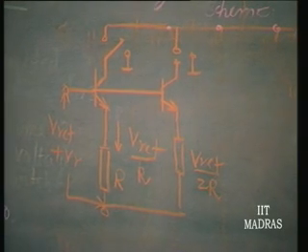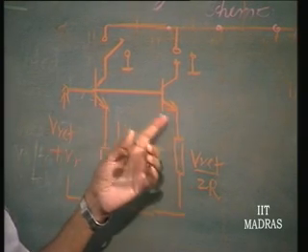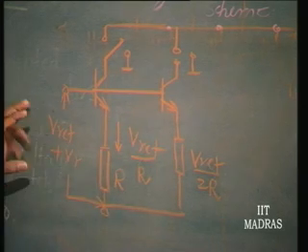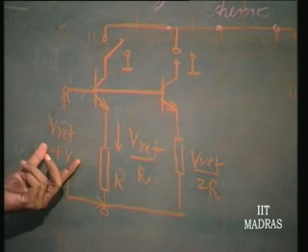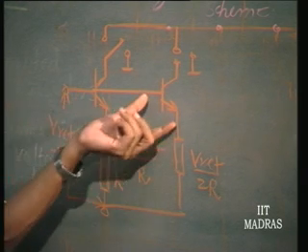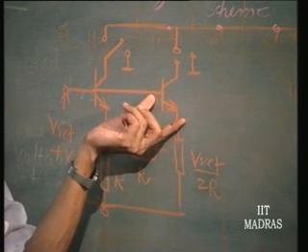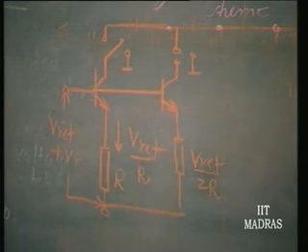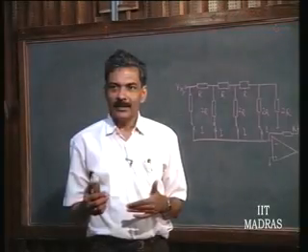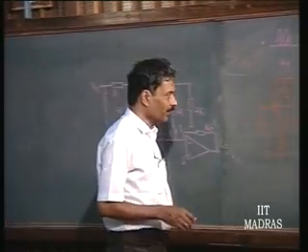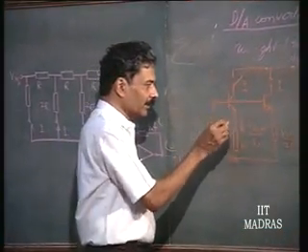It is an established fact that when the current in these transistors varies, the voltages will be different. So, if I have carefully adjusted this V gamma to compensate for this transistor, then it will not do for this transistor. Is this clear? Because all these transistors are operating at different currents varying by a factor of 2. So, that is easily compensated for by making this particular thing.